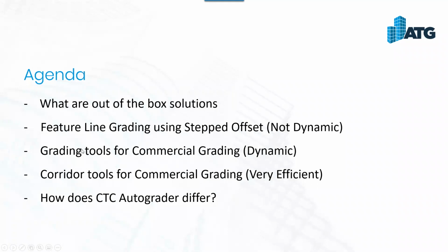Another tool we'll look at is the grading tool in Civil 3D. Now, this is a form of dynamic grading. The one area that I don't like about using the grading tools is that a lot of times we will end up with the little diamonds, and if you don't delete the grading a certain way, Civil 3D doesn't like it and it will corrupt your drawing.